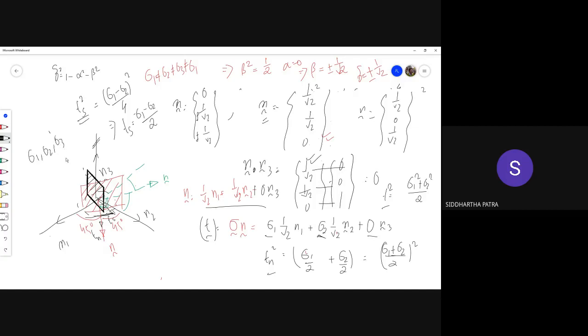It cannot happen that all of them are maxima. As it turned out, one of them is a minima. If I assume sigma 1 greater than sigma 2 greater than sigma 3, in algebraic values, then sigma 3 is the minima, sigma 1 is the maxima, and sigma 2 is kind of the saddle, where you can think of it as neither maxima nor minima.